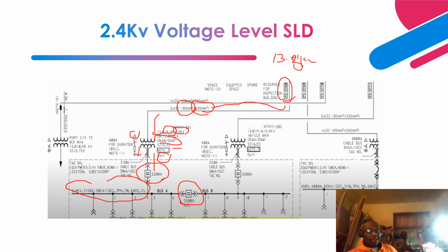So that is when we isolate that bus and close the tiebreaker based on an ATS scheme that detects the level of voltage, and there's a time delay utilizing certain protection relays, that is a sync check relay, ANSI device 25, and a timer, ANSI device 62. So based on that, they sense the loss of voltage on one feed, and are able to close the tiebreaker to achieve that scheme.